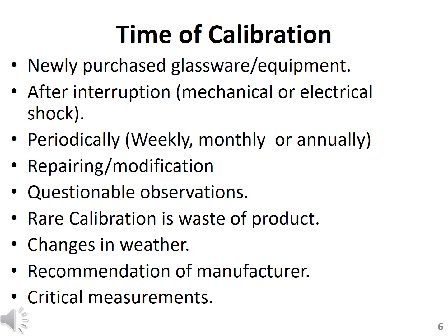So calibration must be done periodically according to the specification, according to the requirement of the machine, given by the manufacturer. And rare calibration will also be a waste of the product. If you only occasionally calibrate, or make a product without calibration, there is a chance that the product will not be of quality.